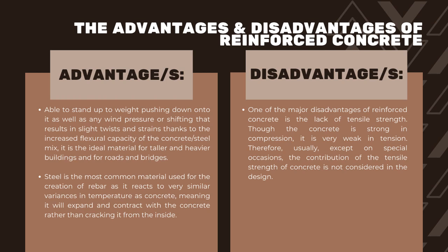Disadvantage: one of the major disadvantages of reinforced concrete is the lack of tensile strength. Though the concrete is strong in compression, it is very weak in tension. Therefore, usually, except on special occasions, the contribution of the tensile strength of concrete is not considered in the design.